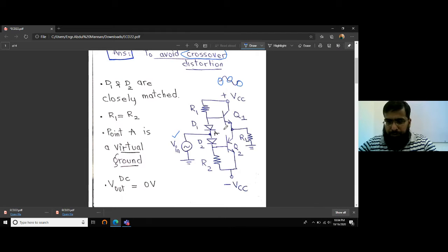These two diodes work like this, for example, let's start from here. The lower end of this RL is connected to ground. This means the upper end is at 0 volts. So if it is at 0 volts, the base voltage has to be at 0.7 volts, right? And this also connects to the anode of the diode D1, and what should be the voltage of the cathode if this diode is also on? Of course, 0. So we get a 0 volt here.